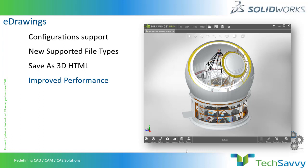But now eDrawing gives you support in a 3D HTML format. So if I save the 3D HTML format, the user who is using a smartphone or WhatsApp can send you the 3D HTML file of an eDrawing. The moment he taps on that file, it will open inside the smartphone, and the user can do each and every type of movement of that view. Not only the movement of the view, it can support its configurations also. So let me show you how we can do that.